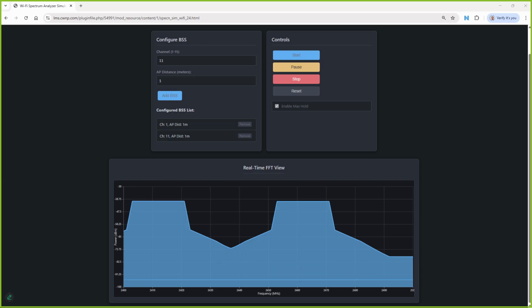Basically, these are the area where it has to fall off by a certain amount of signal strength in order to meet the spec. And then ultimately, the FCC and other regulatory agencies can test a transmitting device to make sure they're in compliance with that spec and that they're not exceeding what they should with their spectrum utilization. And this is what the spectral mask does for you.